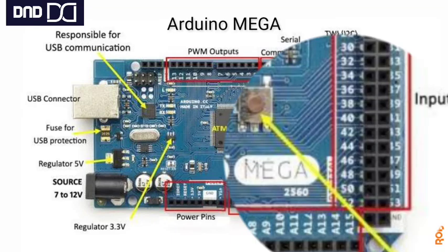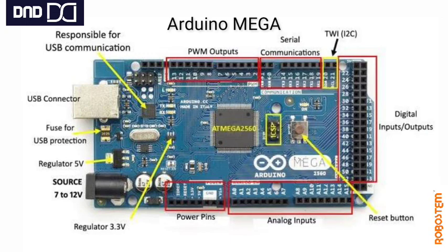That means that many pins, and that is very beneficial for large scale projects. Parallelly, we are having 0 to 15 analog input pins. There we were having only A0 to A6; here we are having A0 to A15. As well, there we were having only 3, 5, 6, 9, 10 and 11 as the pulse width modulation output pins. But here we are having 2 to 13. That means 12 pins; in place of 6 we are having double. We are having 12 pulse width modulation pins.